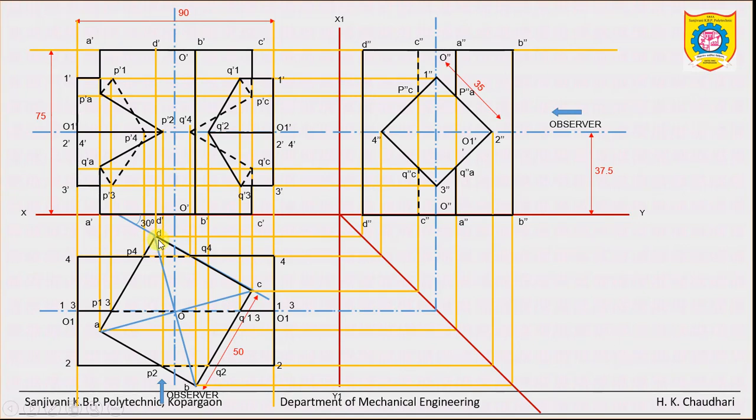D is also outside the intersection, but it is behind this solid. So throughout we can make it hidden. Clear? Now what about the horizontal edges? So all these horizontal edges in between this vertical prism, we can make them hidden in this way.